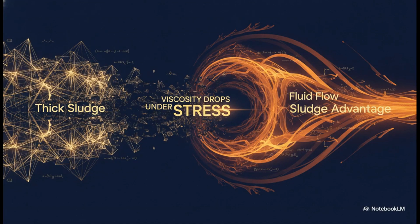Now you might be thinking to yourself, wait a minute, mine waste is a super thick, muddy sludge. Isn't that just going to immediately clog up a vortex? Well, this is where we get into what we call the sludge advantage. A lot of these mine sludges are actually non-Newtonian fluids, specifically shear thinning fluids. Unlike water, which always maintains a constant viscosity, these sludges actually become less viscous. They flow much more easily when they're put under physical stress.